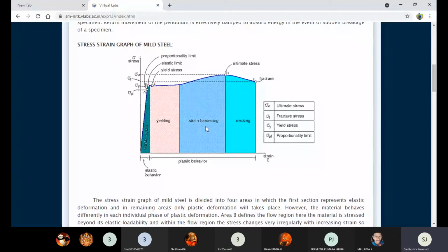Once we go through the tensile test, we need to understand their ultimate stress and their yield point, because the yield point of each and every engineering material is very important. We can understand the yield strength of that particular ductile material, as well as stiffness, through the tensile test only. We can understand the stiffness, yield strength, ultimate strength, and also the fracture point of that ductile material.